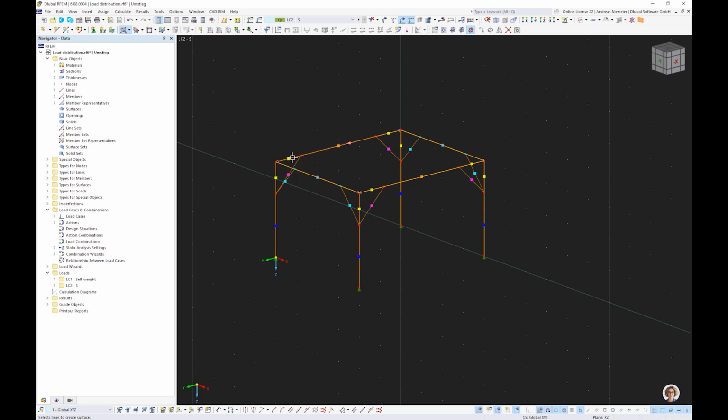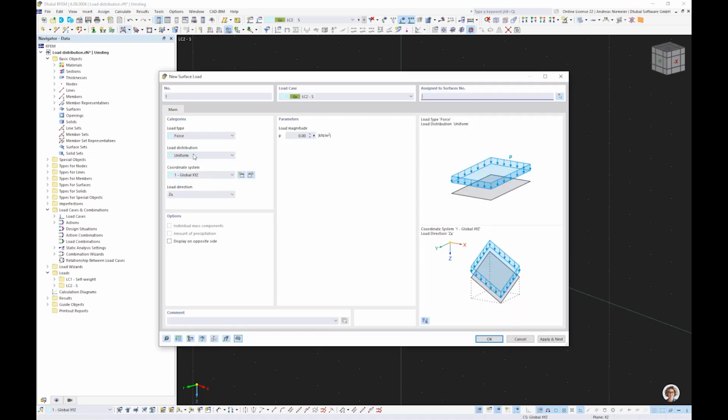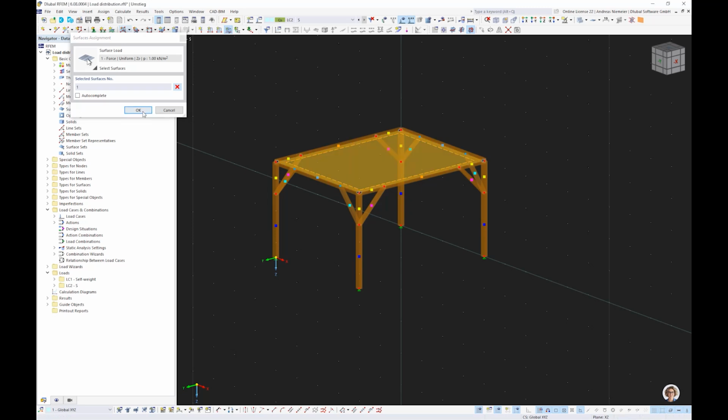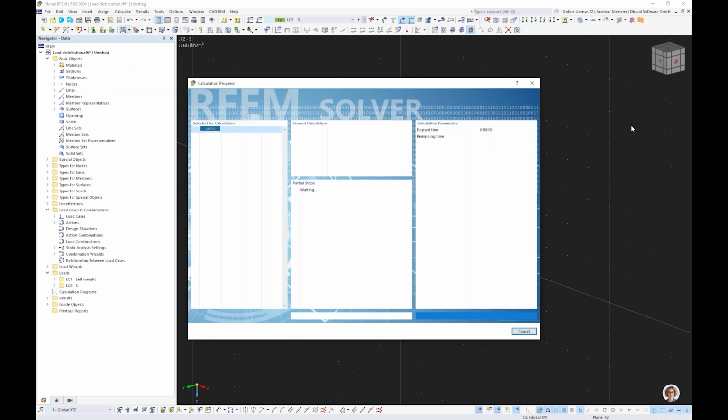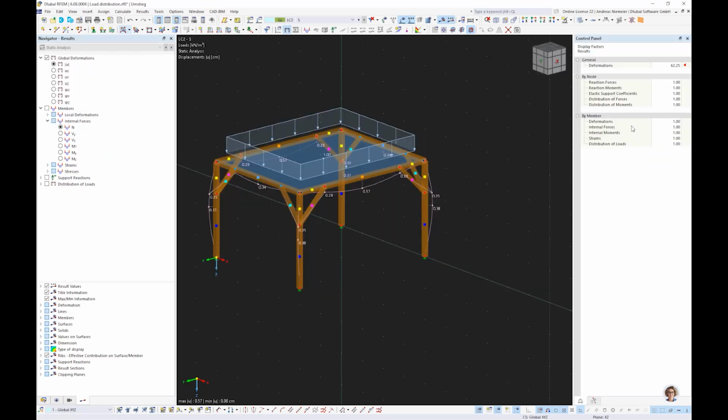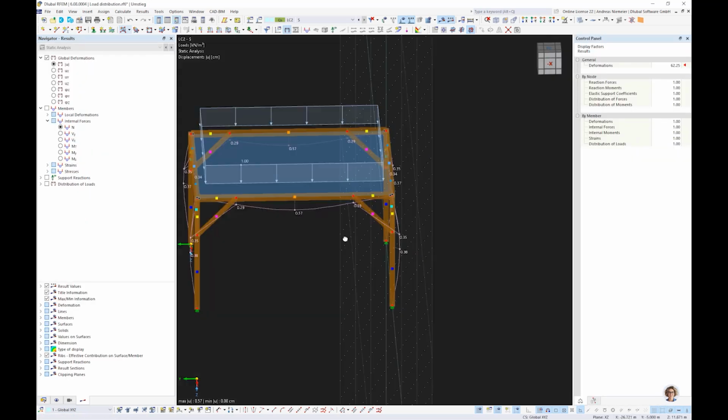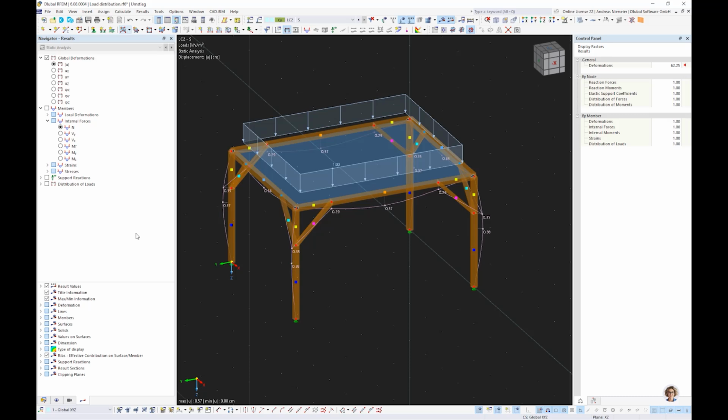Yeah, and now we have the surface inside. You see it in rendering, and now of course you can apply here maybe a projected snow load in Z, standard size is 1, and apply it. And if we calculate it, we get, let's say, forces on the structure, although this surface has no effect. So pretty cool. We have no surface forces.